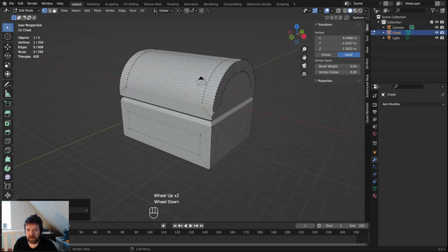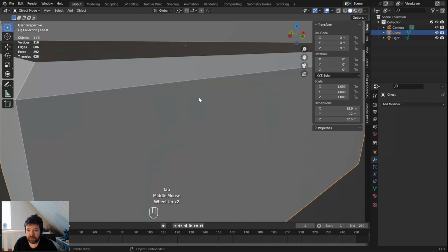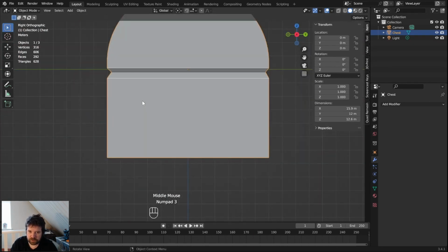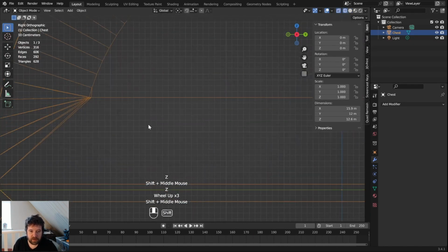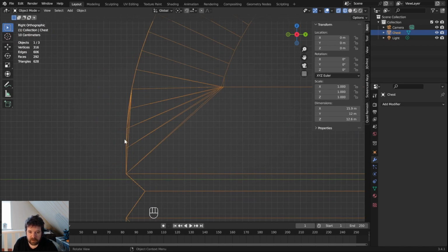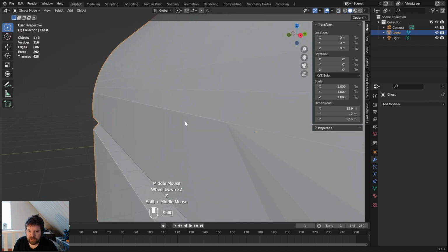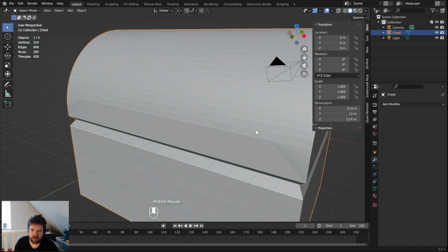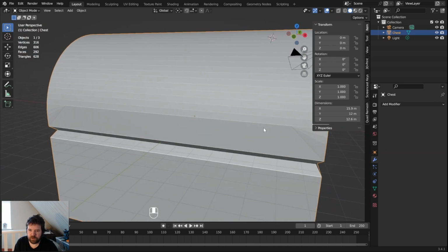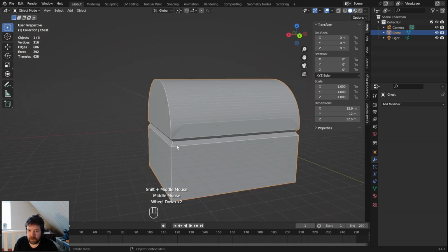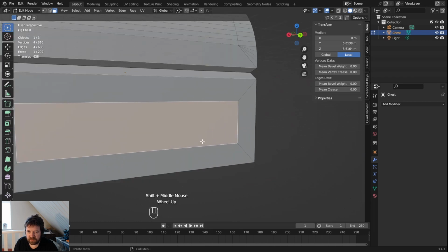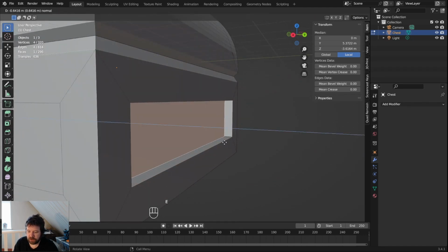Right, so we have these self-intersections. We see here that it looks a little bit strange geometry here. It's nothing incorrect. I think that when we print this it won't be visible. The computer view enhances it. So let's do the actual insetting here, or not insetting. We want to extrude inwards 0.5 millimeter.